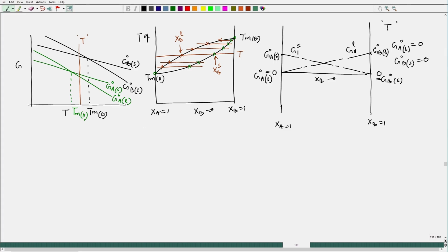And we know that G2 solid/liquid would be equal to G1 solid/liquid plus ΔG mix solid/liquid. So if we take solid solution, everything should be solid, and if we take liquid solution, everything would be liquid. So even the composition, we have to assign the liquid composition. Now G2 is the free energy of the solution, and G1 is the free energy before mixing, the unmixed condition.